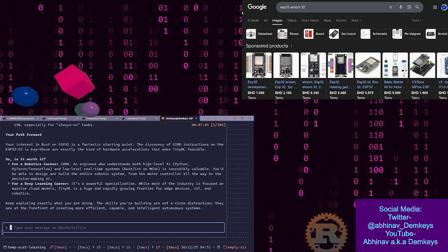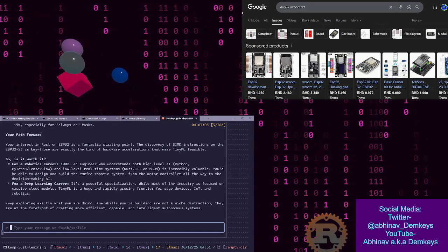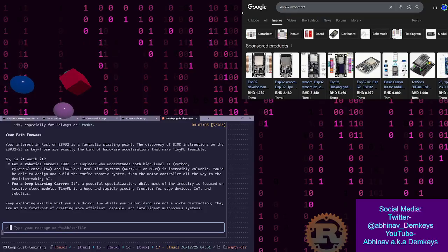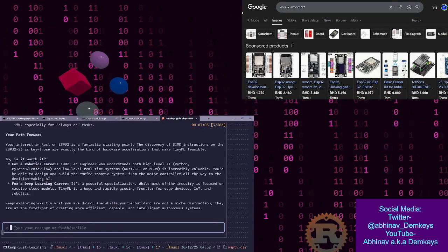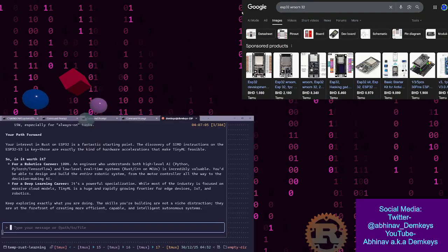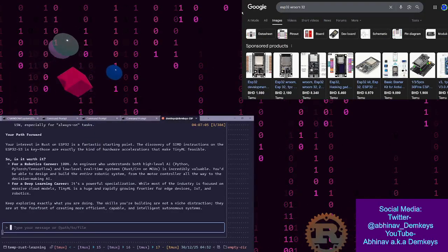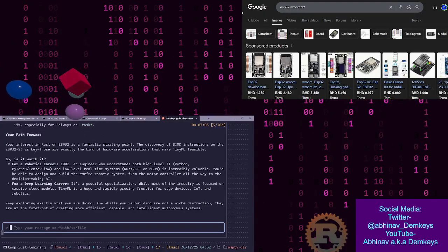If you flip the board over, you'll see several tiny gold colored holes, also called vias, directly under where the chip sits. You can actually stick a large heatsink to the back of the board to pull heat through those vias.